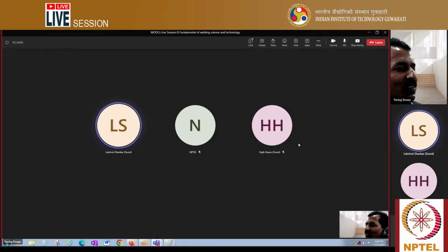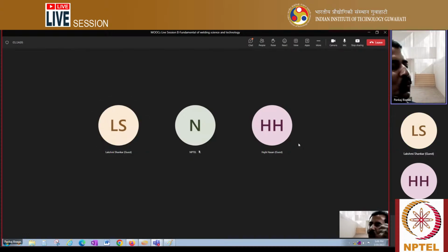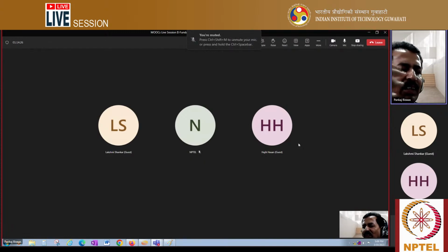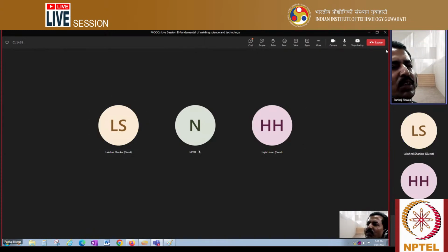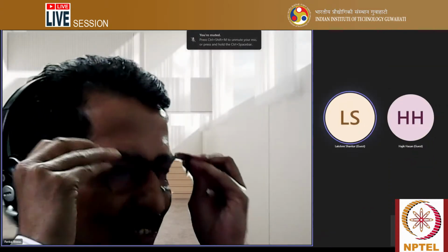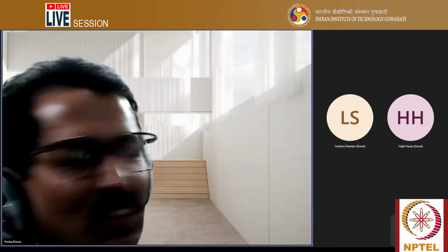You can play on your own, because if you know the fundamentals, if you want more deposition, you need lesser welding speed and high heat input. To get high heat input, everything is now known to you. Generally different parameters are decided for different types of material. Clear? Any other questions?